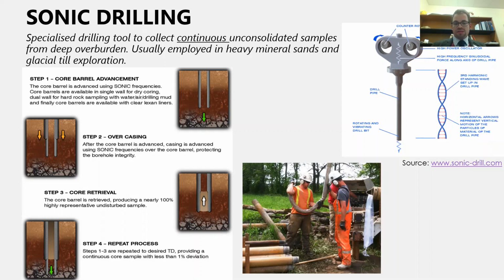Sonic drilling is commonly used when the question is about obtaining an uncontaminated sample in soil. I've seen it being used particularly when it comes to glacial till exploration, when you want to obtain a continuous sample through a number of meters of till, and sampling at the bottom of that till package.